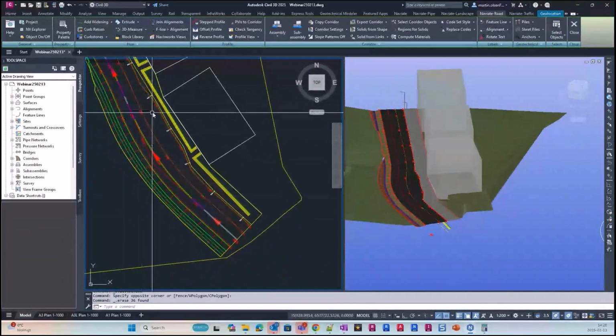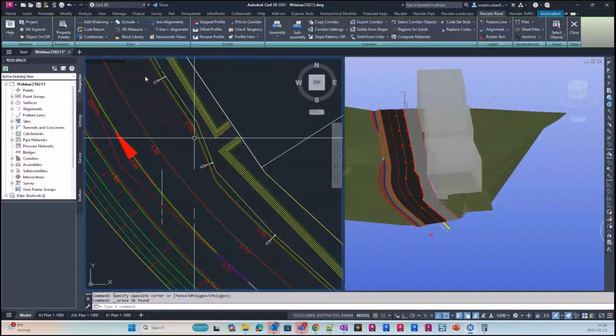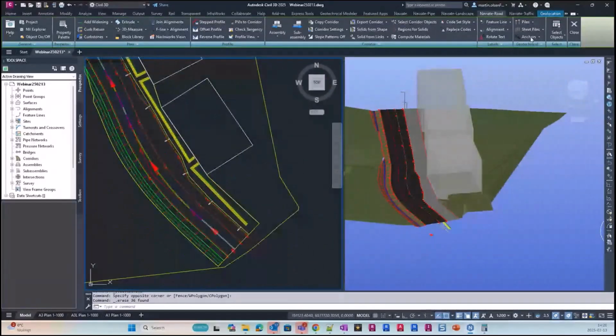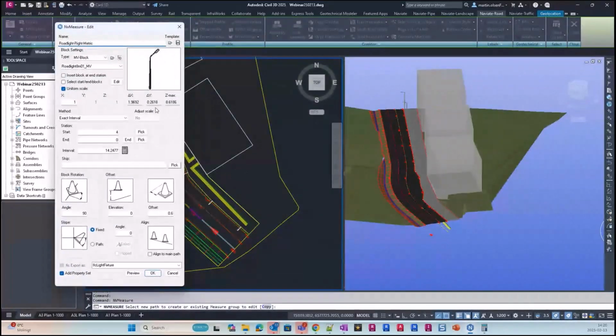Now that I have created these lighting poles, I also want to remove some of them. So we have also added the feature to be able to skip objects or detach from the set if you like to do that instead. I just pick an object to get the settings again, and then I choose skip here.